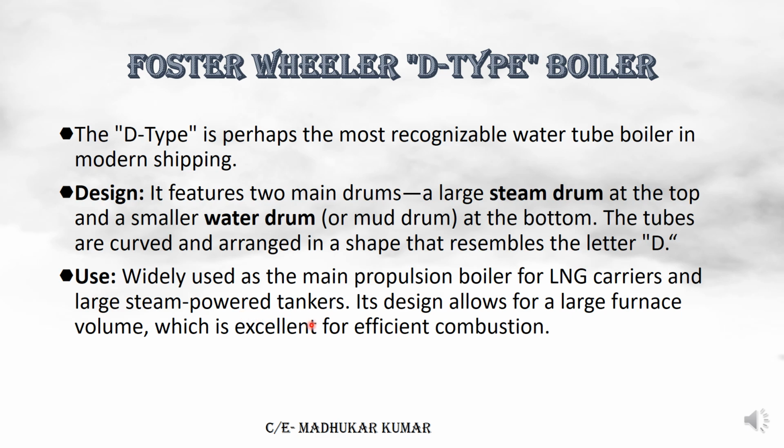Widely used as the main propulsion boiler for LNG carriers, large steam-powered tankers, and its design allows for a larger furnace volume and efficient combustion. Not only that, the response to high load demands is also very good. So this is Foster Wheeler D-type.